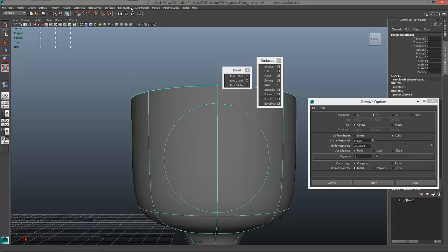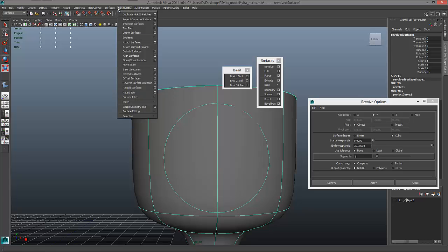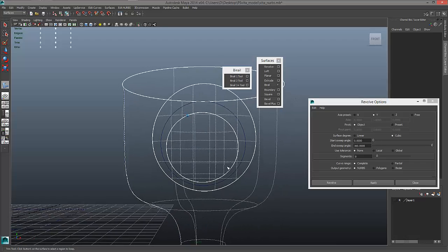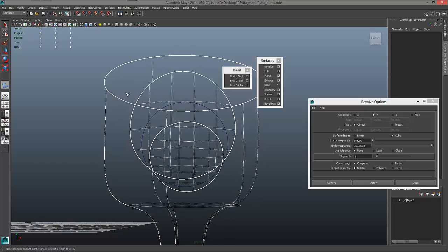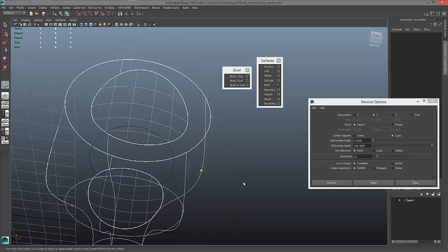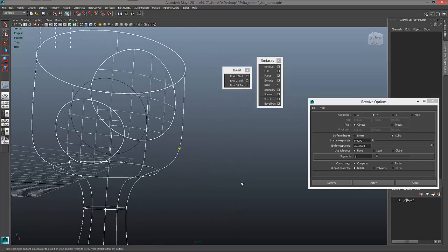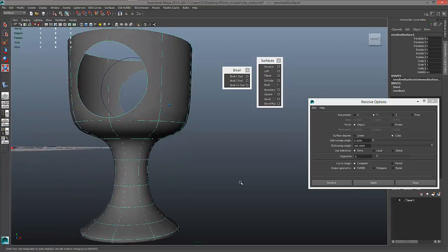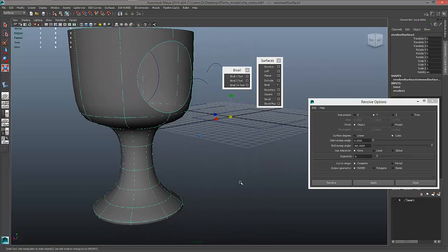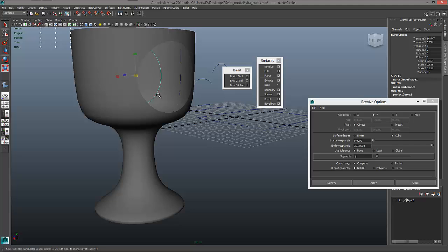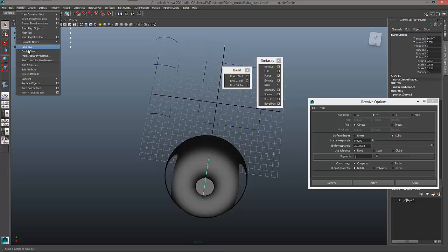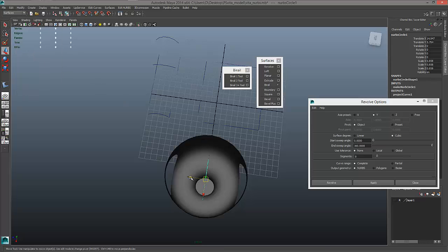When I do this, I'm going to select my object. I have curves on surface. I'm going to select my object, and I'm going to come in here and say trim tool. And you'll notice that everything has these dotted lines to it and kind of these border lines around the edges. If I click on a dotted edge like this right here, it would actually make the glass solid. And when I hit enter, the computer knows what's left over inside of the trims that should be cut out. So that's actually a really cool way to make cutouts into objects and get it done with relatively no muss, no fuss, just to get something clean.